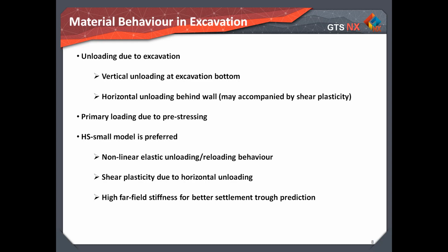Jardine states that a review of published analyses strongly suggests that the lateral wall movements are not very sensitive to the type of constitutive law adopted, at least as far as excavations in stiff soil are concerned.